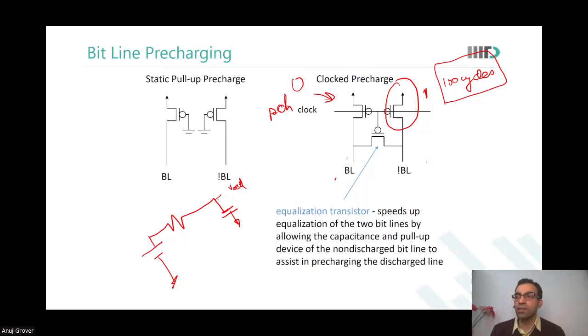Right. So it got much less time, and therefore the precharge will not reach VDD. There will be some residual difference between one bit line and the other. The VDS would appear and then it will equalize, sort of.